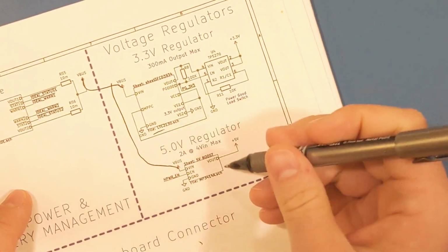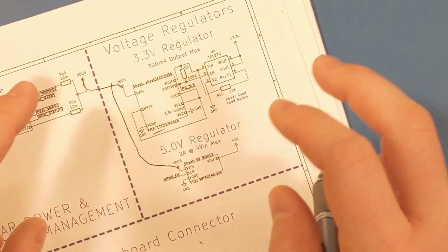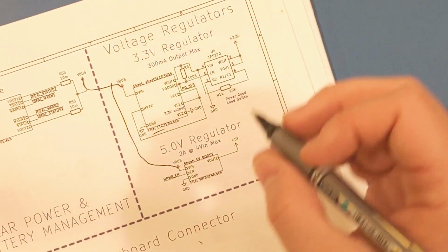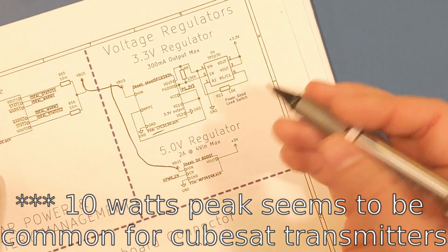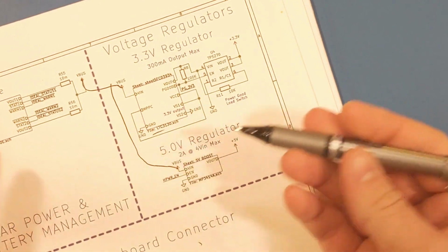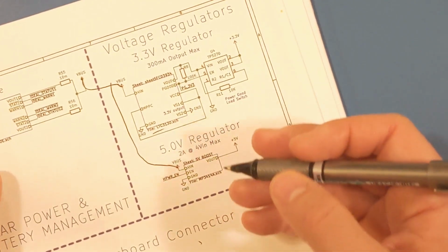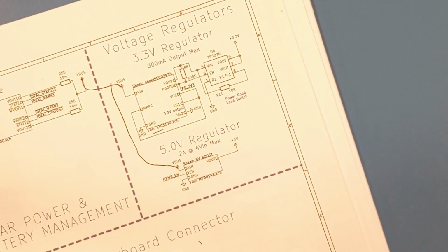I've picked this because I know I'm going to be using some sort of high power-ish radio. I mean, high power in that it uses maybe 10 watts peak for a couple seconds, which based on my research seems to be pretty common. So I wanted 5 volts, which is just a generic enough voltage. I was hoping to find 3 amps, but 2 amps seemed like the most reasonable thing I could find in a package size for a chip that was easy to install.